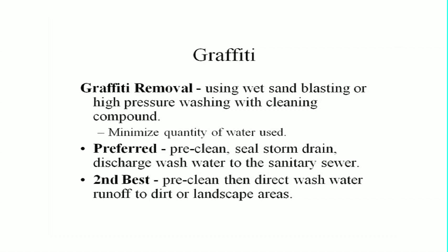Graffiti removal, using wet sanding or high pressure washing with cleaning compound. Minimize the amount of water used. Pre-clean and seal the storm drain and discharge the wastewater to the sanitary sewer. Second best, pre-clean, then direct the wastewater runoff to a dirt or landscaped area.